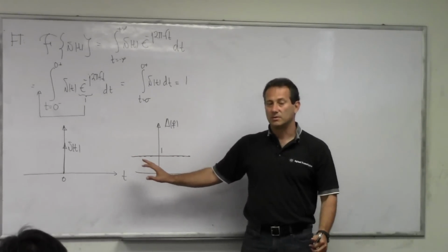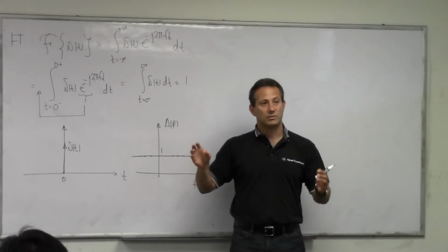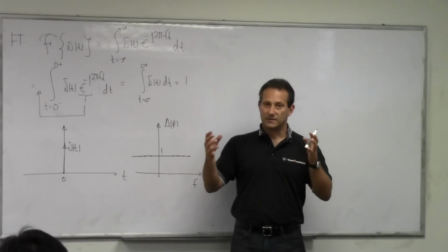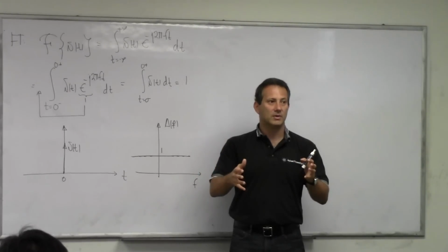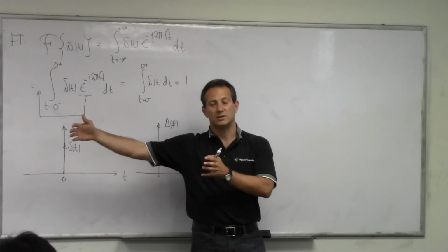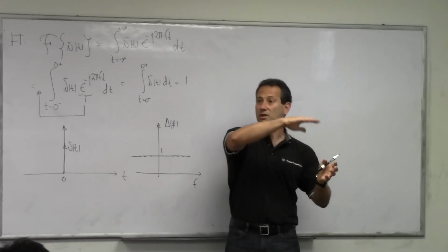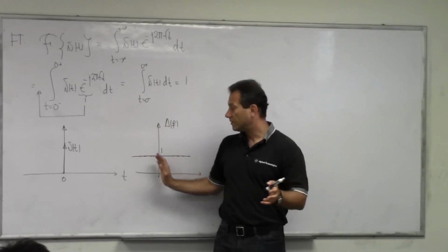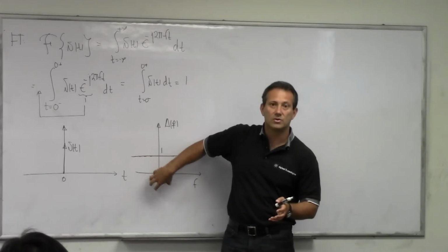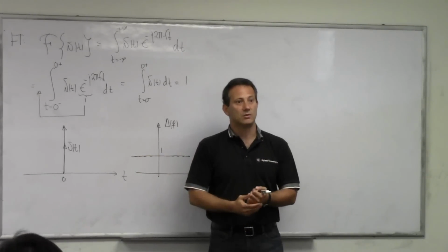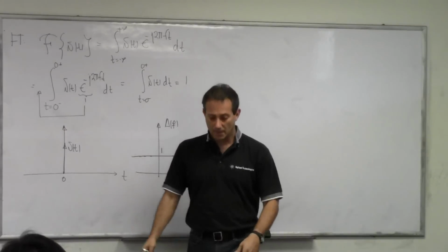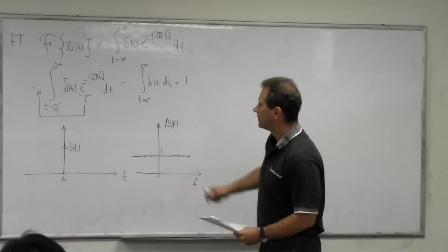And we'll follow this observation all along. What you will find out is there is something called the inverse time-frequency relationship: if the phenomenon is fast in the time domain, it is going to be very rich in the frequency domain. In other words, it will need higher frequency sinusoids. Likewise, if something is changing slowly in the time domain, the sinusoids that you're going to need to build it are going to be concentrated around 0. They're going to be low frequency components, just because the whole phenomenon is moving slowly. So your bricks are big. All right, so that's the first example.